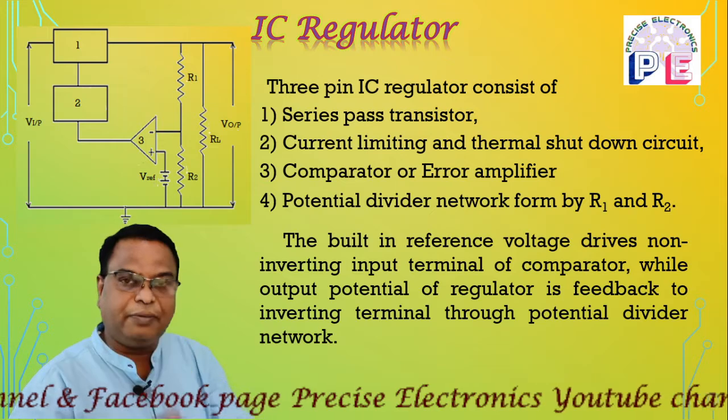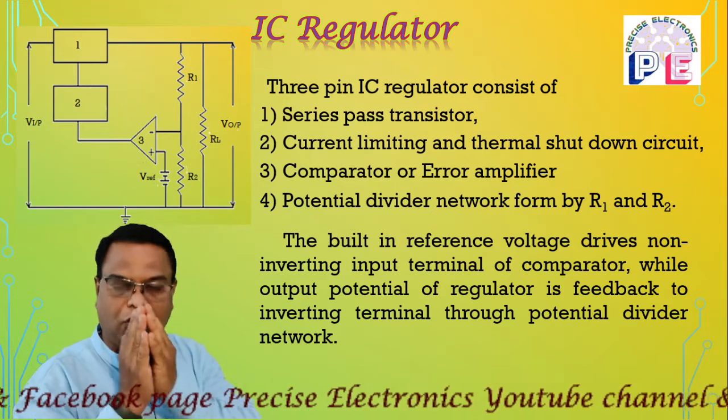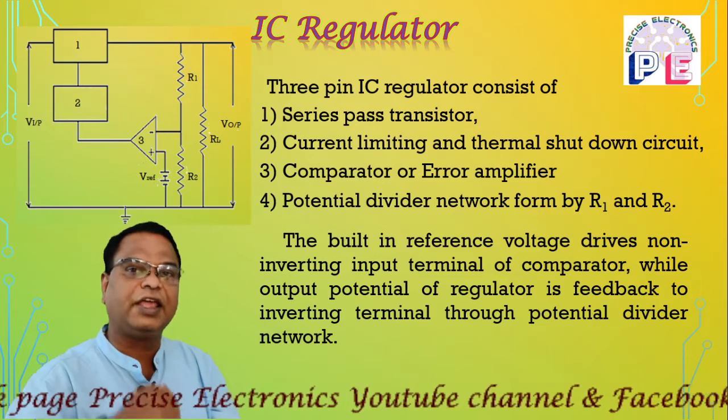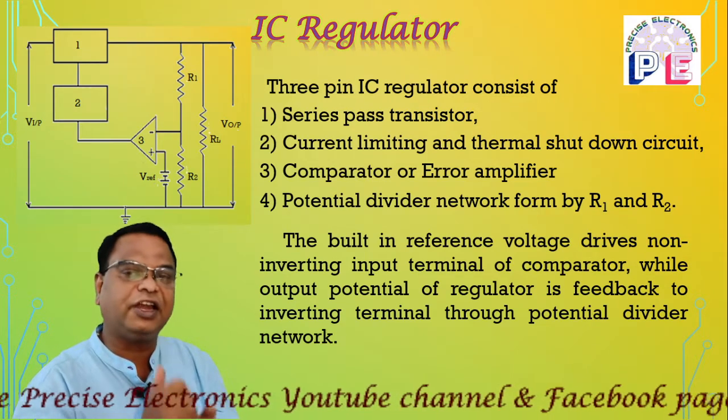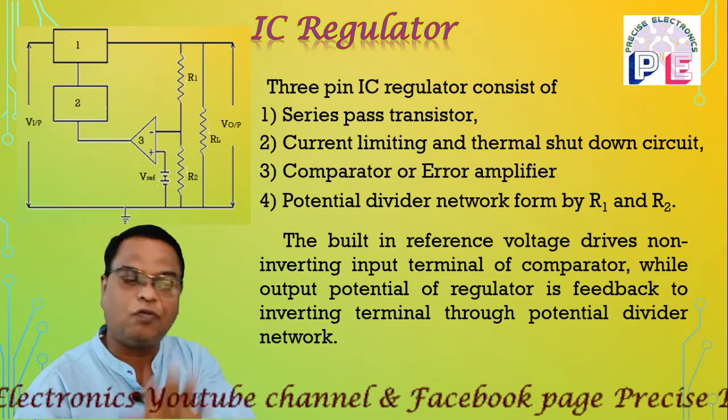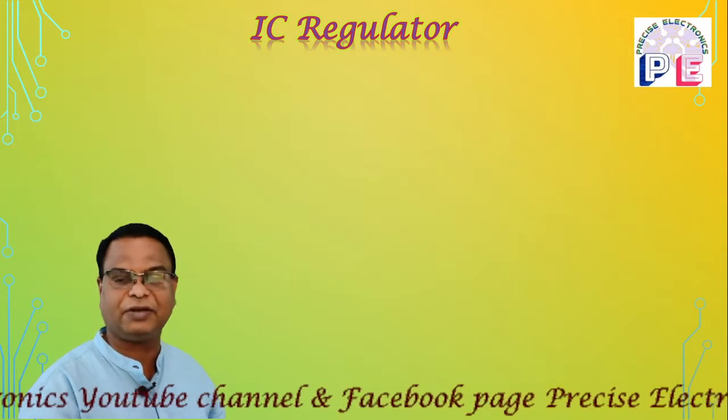So the inbuilt reference potential, which is a fixed potential, is connected to the non-inverting terminal, and the output voltage is fed back and applied to the inverting terminal of the comparator, or the error amplifier.